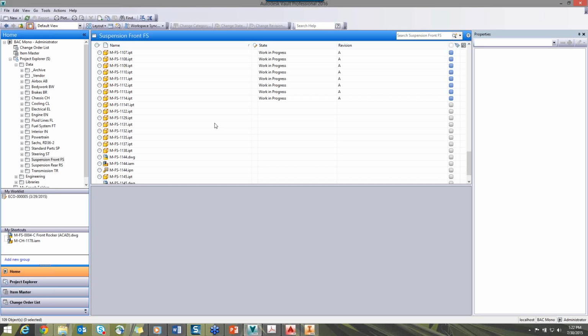Also, one thing that I want to point out with what they call AnyCAD and DWG underlay as a part of that, you also have the capability of referencing non-native Inventor files such as SolidWorks, Pro-E, Catia, within an Inventor model. So we know that we have certain companies that might have a mixed environment where they might have SolidWorks and Inventor.